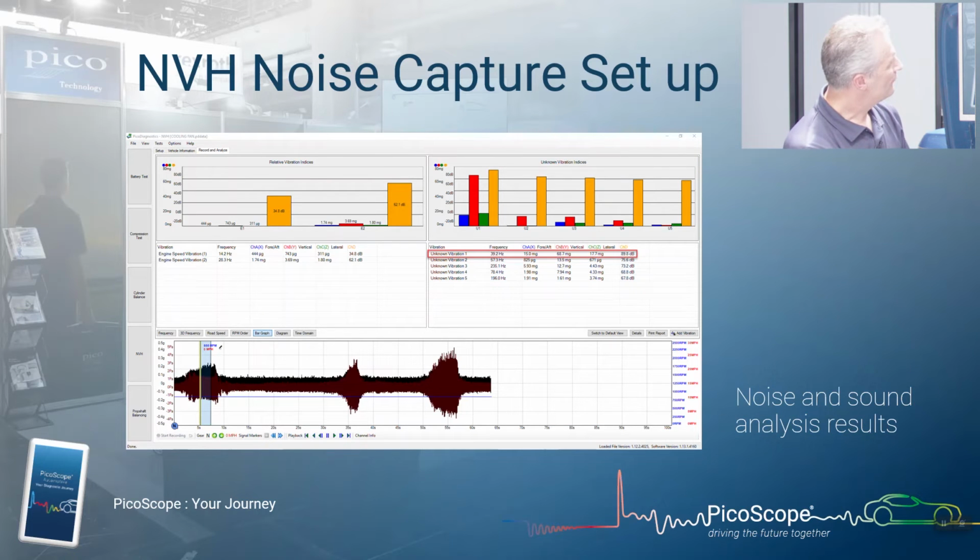Here it is. I've moved the marker here to concentrate on the vibrations and noises just in this zone. So we see where the amplitude is at its greatest. And then here we can see unknown, the yellow peak in particular, 39.2 hertz. Now that is a cooling fan speed, cooling fan frequency.